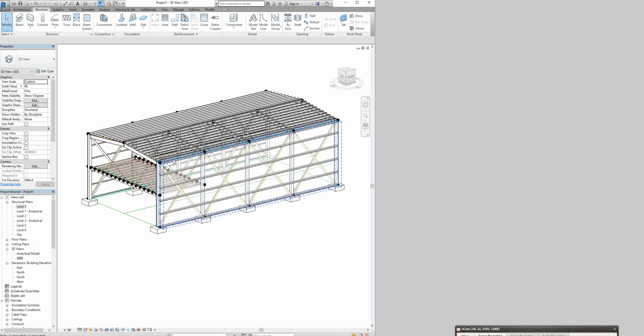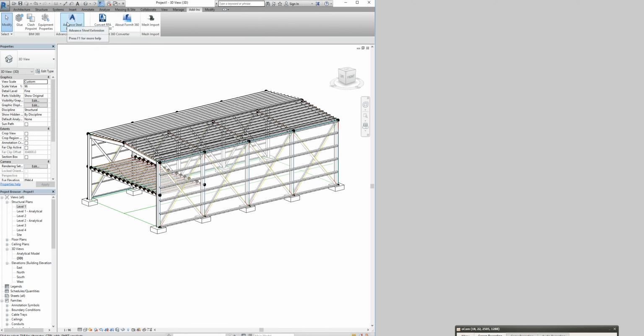So basically, all these black point dots are like a guide for where we need to put any connections, and that's what I explained in the Autodesk Advanced Steel slide. So I'm just gonna talk a little bit about detailing and how Revit and Advanced Steel have an add-in that you can put in Revit. It's actually here, add-in, Advanced Steel extension, and you can use this one as a basic concept model that you can export into Advanced Steel and do all your plates like welding or bolted connections or anything, and it's quite useful. So that's all the black dots. It's just for indication of where connection should be.